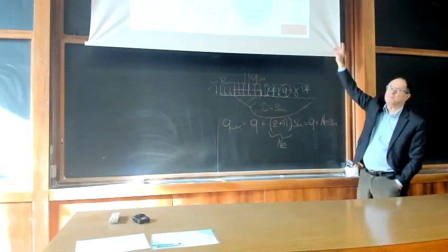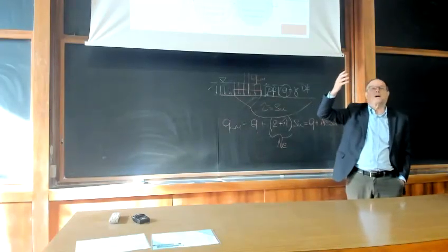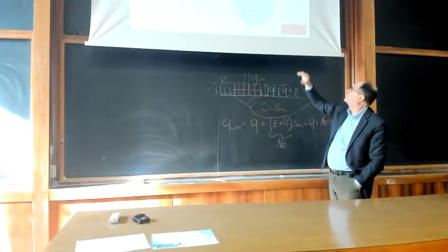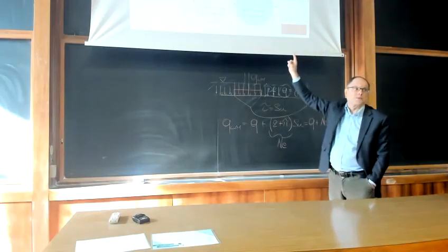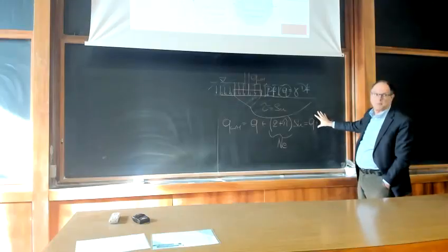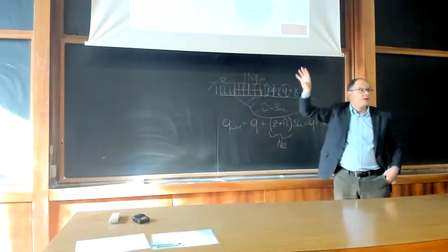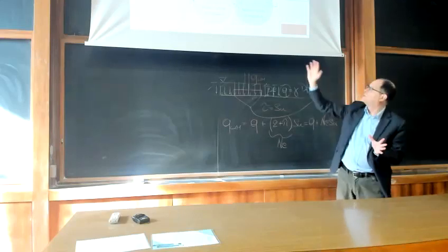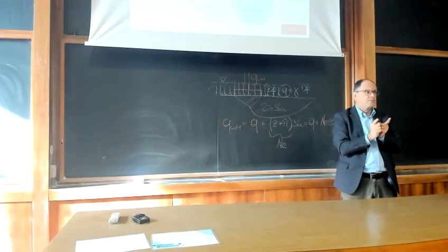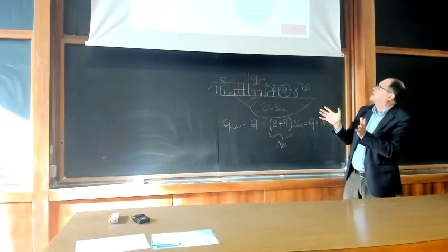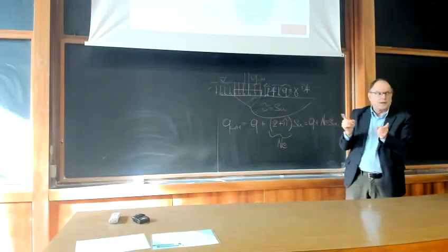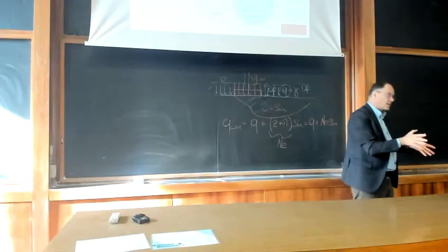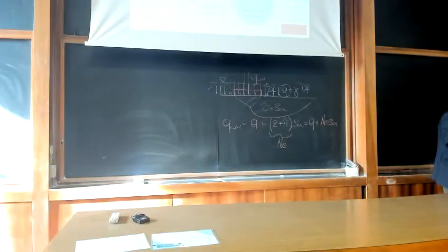with another solution provided for the same situation, but making use of the lower bound theorem, getting to an expression which is Q plus 4 SU. Okay, very similar to this. This is an upper bound, this is a lower bound. The true load under this assumption is in between the two. So the better we are, the more able we are to match the two theorems, the closer we go to the exact solution. Remember, always an exact solution under the assumption of the plasticity theorems.